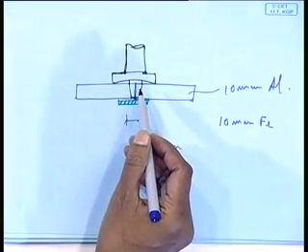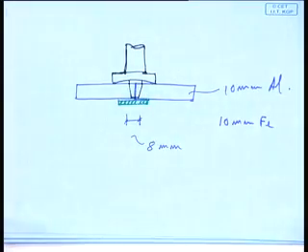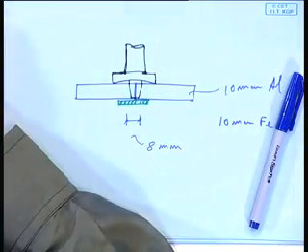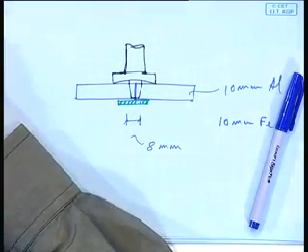And to make it sufficiently softer to apply the solid state welding process, you have to raise the temperature much more. You will have to attain around 800, 900 or probably 1000 degrees centigrade, right. So there again this diameter will matter, how much you are putting. Anyway, these are some of the aspects which will decide the diameter of the tool nib.